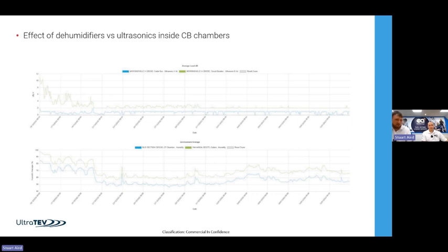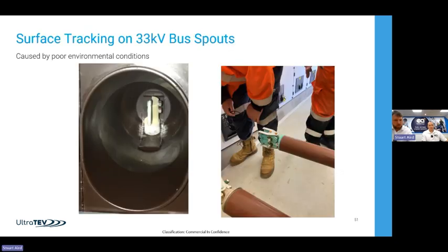So controlling humidity, heading down to the 55 mark, will make a massive difference to how often that activity is sparking, how quickly it's degrading, and the likelihood of it starting. And that's shown there on the trend of the two graphs. So what was it? This is enabling because the customer sent through a fantastic video, which I'm going to show you on the next page and give you a feel for what PD really is.